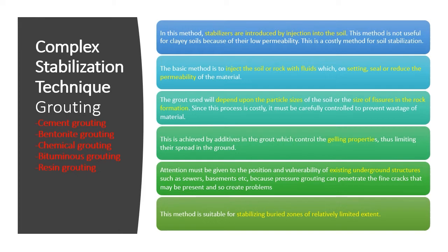As the grout enters the void, it forces itself into the void cavities and fissures in the soils and rock. In weak soils, it will displace and compact the ground as it fills the void. As the voids are filled, the ground becomes stiffer, more stable, and water resistant. Pressure grouting can also be used around basements and cofferdams to reduce hydrostatic pressure on the structure. To create a water-resistant barrier, the bores and subsequent columns of grout are placed at close centers.